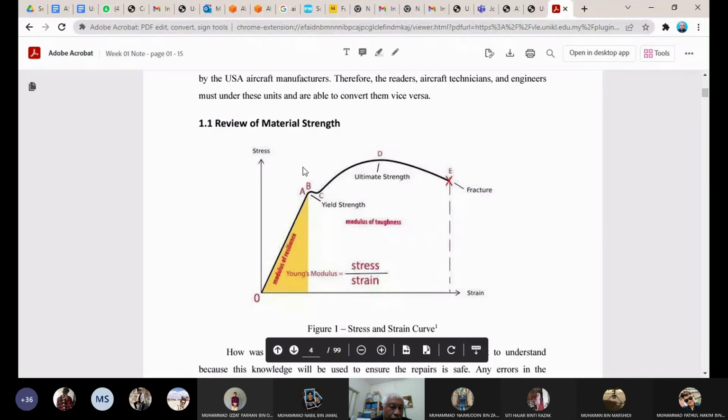Then at a certain time it no longer deforms linearly. This is the linear region, then it starts to yield. Yield means you don't increase the stress, however the structure continues to elongate, or you can say also creep. We apply a very small load and get small stresses, however the elongation is large, it is easy to pull the material apart.